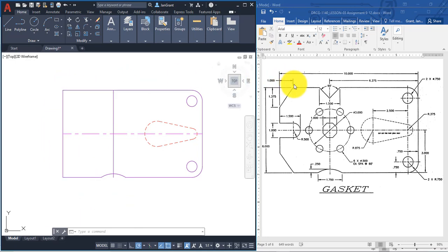You could be resourceful and just draw lines and then draw the diagonal, or you can use the chamfer command. The chamfer command is really great because it's sort of like fillet, but you're based on a distance from the corner. So if you take a look, we have distance 1 potentially as 1, and then distance 2 is 1.375. So I think it would be a great idea for you to use the chamfer command. Let's go ahead and start the chamfer command.